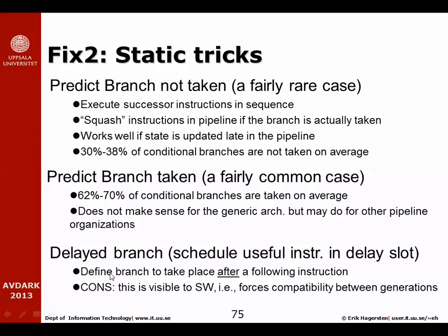So let's say this branch hazard adds 1 useless cycle, 1 bubble in the pipeline. Let's by convention decide that that bubble in the pipeline is not a bubble. It's always going to be executed. And ask the compiler to do its best to fill that slot with an instruction that would have been executed anyhow. And if it cannot find any instruction to put in that slot, it puts a no-op operation that will do no harm. So the first time I saw this idea, I thought it was a brilliant idea, because now we completely solved the branch hazard, the control hazard problem.